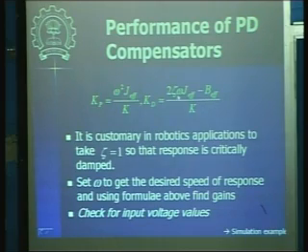Now omega selection you can do based on how fast you want to move. Now again recall the trade-off that I have told you already, that you can ask the robot to move from one point to another point as fast as you want, but you have a limitation on the actuator. So there is always a balance between how much energy you have, and how much performance you are desiring out of your robotic system. So this trade-off you have to balance and accordingly choose this frequency omega, and then your gain values will be in place.